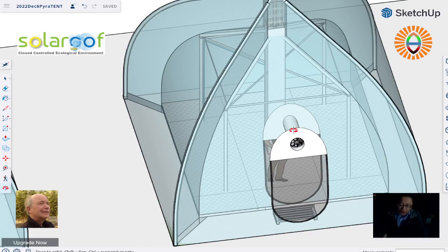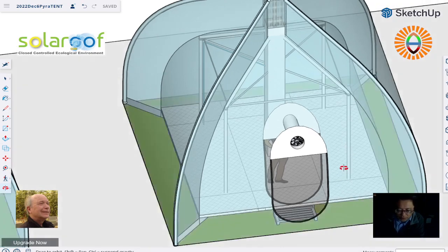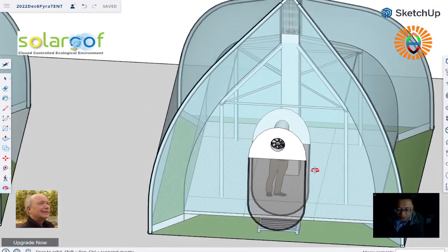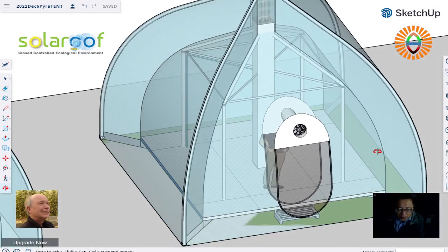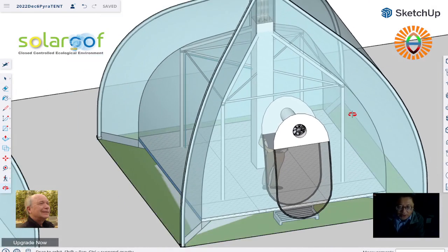The air blowing in, and then the inner air coming out from the double layer cavity, right? And then there's heat exchange, automatic heat exchange as the air goes in, and the inner air goes out. Very easily you can have something like that, and this way you can recycle the heat. You don't lose the heat too much, right? So that's it.